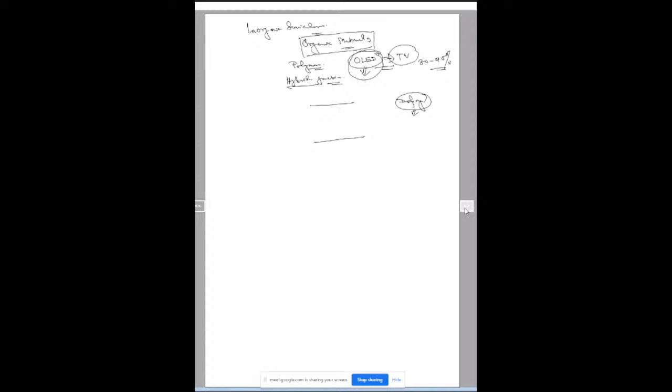A semiconductor in the purest form is an intrinsic semiconductor. Intrinsic semiconductor means it is 100% pure semiconductor, which is not possible, right? None of the materials can be obtained 100% pure. There will be some impurity, so an intrinsic semiconductor is something idealistic. It means there is no impurity in the semiconductor. You will have a valence band and a conduction band, which can be shown like this, and this entire region in between is completely forbidden. There is no allowed energy state.